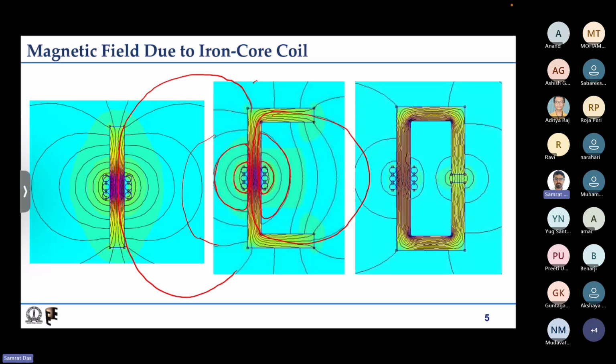After that we saw the case for iron core with a very small air gap, and we have some turns around it, so we can create very high flux density in air, and that is important. So flux density is high, and flux density by mu 0 is also quite high compared to iron. Whatever is the flux density, almost the same flux density is here also, but when calculating H, it has to be divided by the mu r of the material, which is tens of thousands, but here it is mu r equal to 1.